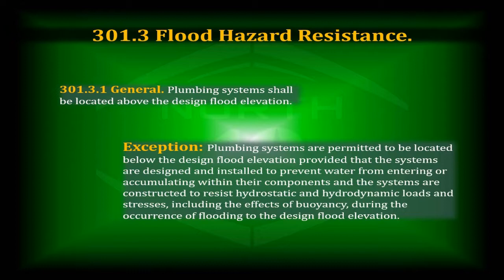And there are some exceptions. Let's look at them. Plumbing systems are permitted to be located below the design flood elevation, provided that the systems are designed and installed to prevent water from entering or accumulating within their components, and the systems are constructed to resist hydrostatic and hydrodynamic loads and stresses, including the effects of buoyancy during the occurrence of flooding to the design flood elevation. Now, what does all of that mean? There's a lot of busy work going on there. Well, what does all that mean?